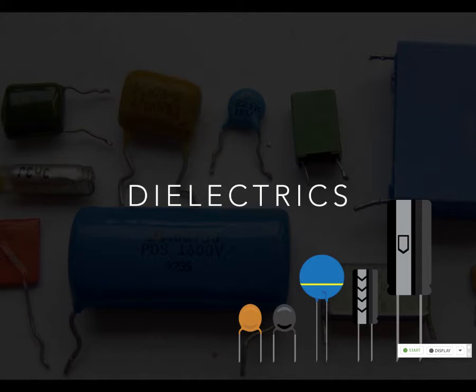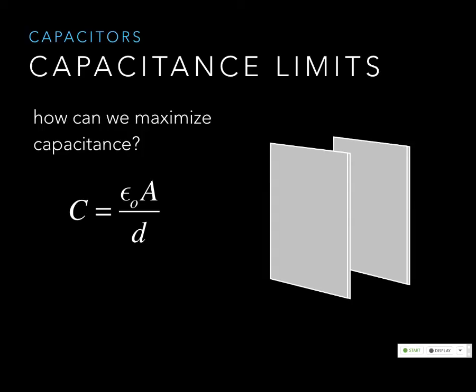These are all different looking capacitors. They're cute. Except there's some giant ones. Have you ever seen the capacitors in like an AC unit? They're gigantic. Like I think I have one in my office. It looks like a little tiny canteen, you know. So, yeah, they're crazy. Stick your finger and touch it. Just make sure it's discharged first. That's why you want to make sure not just to unplug the power, but see if the capacitors are discharged before you work on large electrical systems.